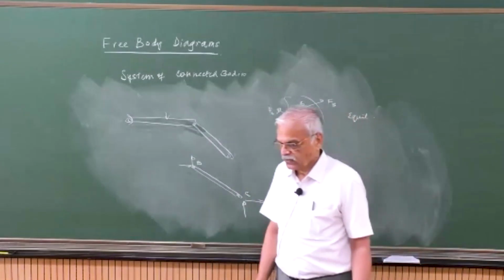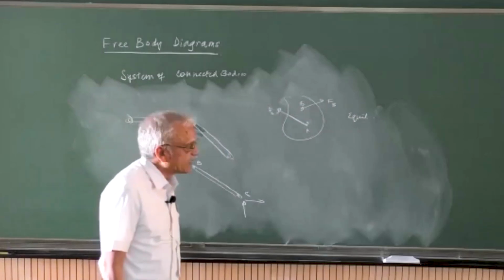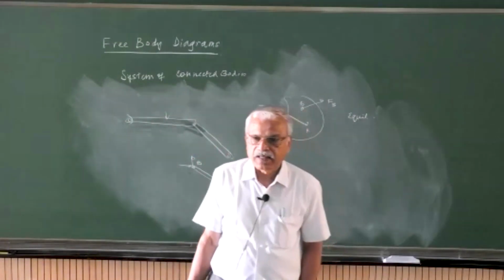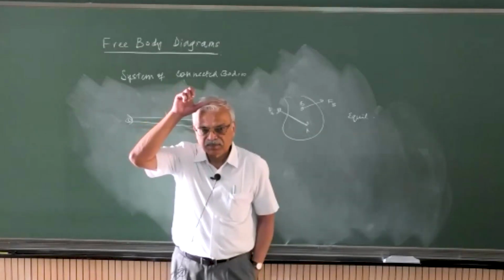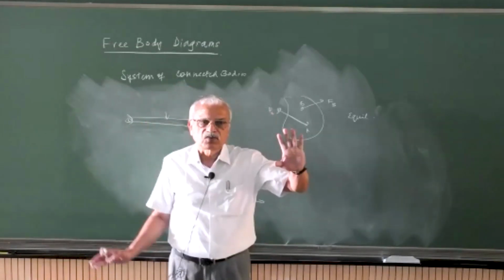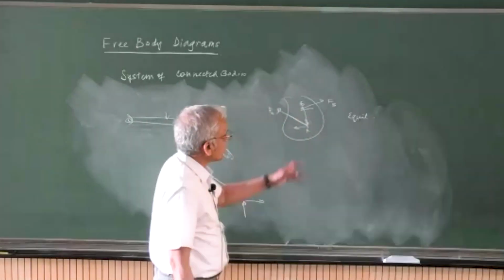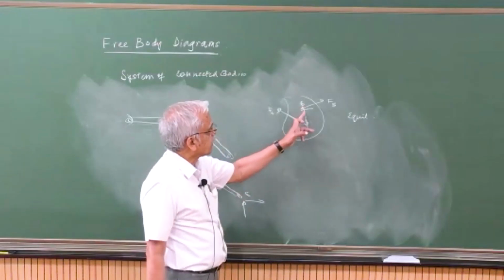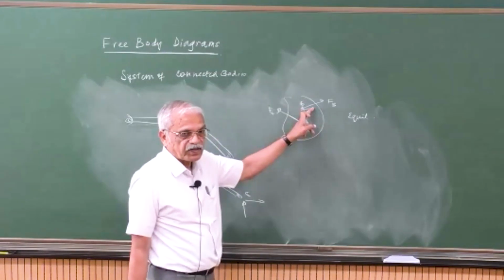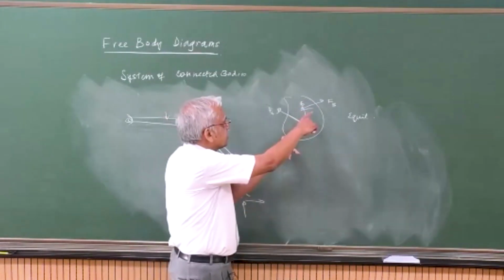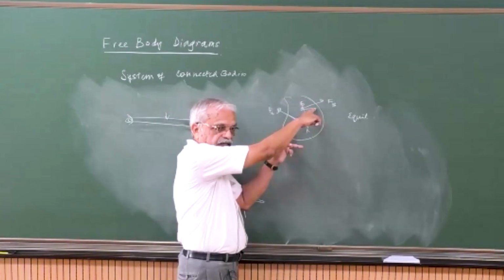Yeah, you have used it in your earlier physics problems. Can you tell me any condition on FA and FB so that the body is under equilibrium? It's only acted upon by two forces, one at A, one at B. Okay, resolve them into two components. So there are forces along AB and force components perpendicular to this one. What is the problem? If this is under equilibrium, obviously these forces have to be equal and opposite.